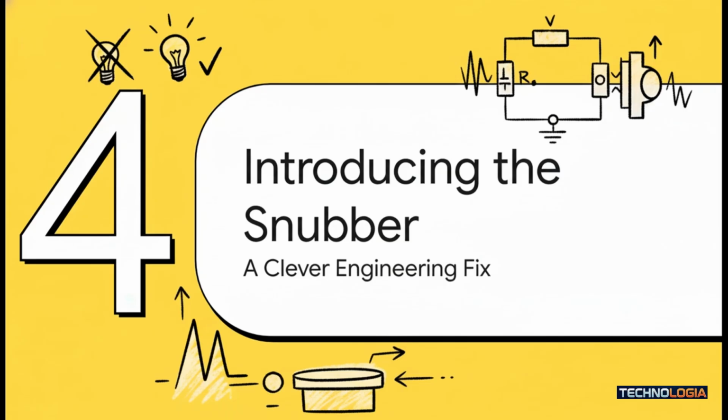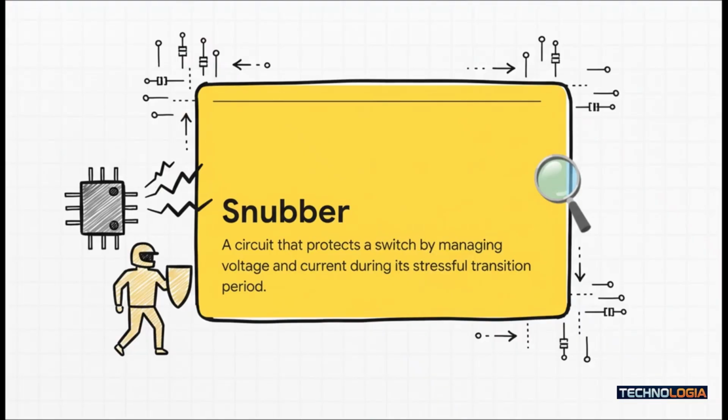Well, engineers, being the clever people they are, came up with a really elegant solution. It's called a snubber circuit. The best way to think of a snubber is like a personal bodyguard for the main switch, the transistor. It's this small secondary circuit, and its only job is to jump in during that stressful transition period, take the hit, absorb that energy spike, and protect the main switch from getting fried.